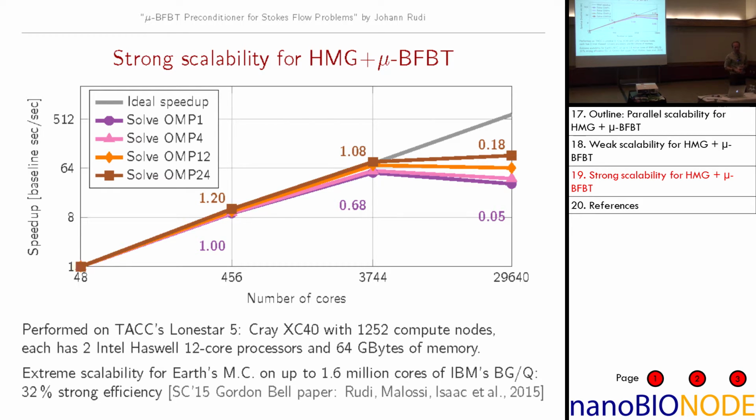Yeah, so it depends, of course, on what kind of problem you're solving, what kind of viscosity you have. There are tests where I compared the HMG with just plain AMG. And it turns out that by knowing these features of the finite element discretization, knowing the problem, and using these high order projections, I could always have a convergence rate better than with just plain AMG.